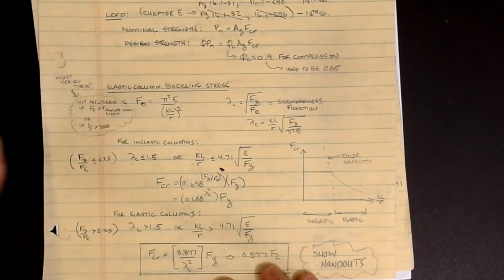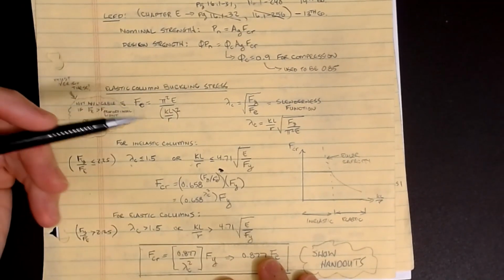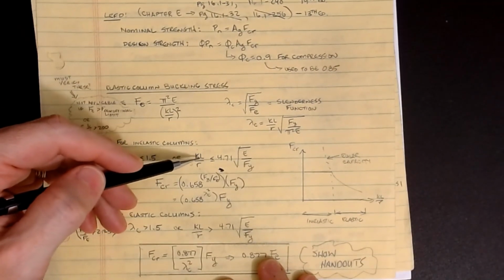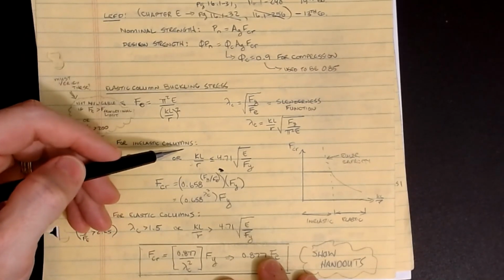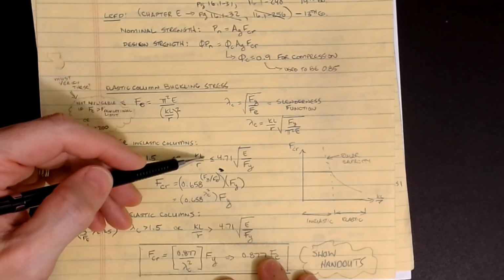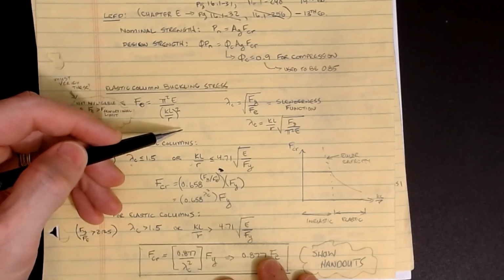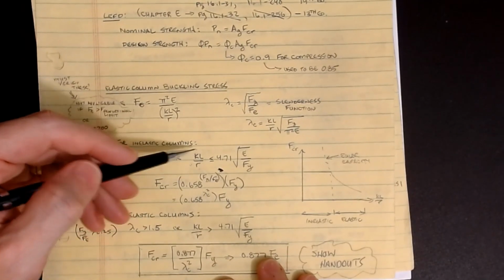Okay, now for an I-beam, which most columns and buildings are typically made out of W shapes or some wide flange shape, you know that there will be an RX and an RY associated with that. So you have to calculate KL over R for both directions. And in fact, depending on the framing conditions, you can have different lengths of columns in each direction. Like say you brace it in one direction but not in the other, well then it's harder to buckle in one way.